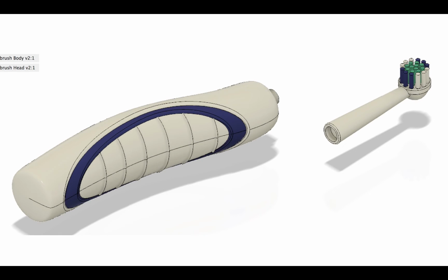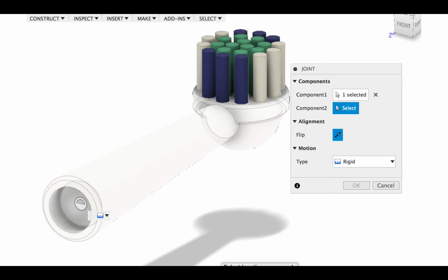And the position I want to move it to is just kind of off to the side. I don't want to try to eyeball it. I want to be more precise and create an actual assembly. So I just bring this into the side here. And then I can create a joint. So Fusion 360 has some assembly tools. Joints are how things are connected.